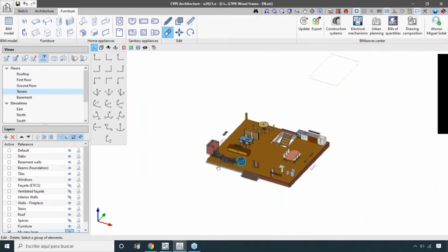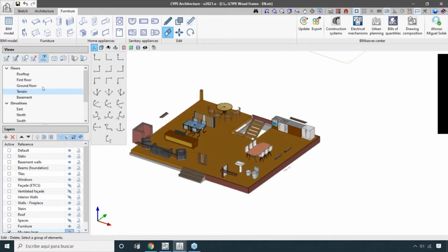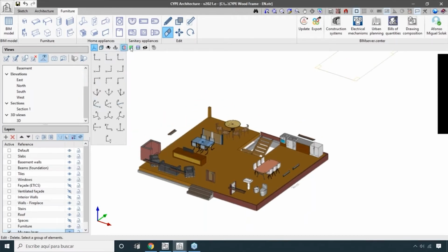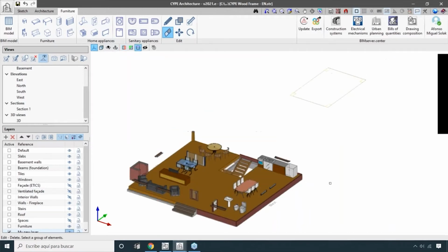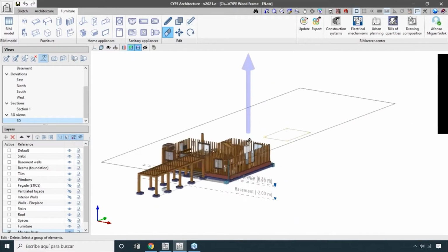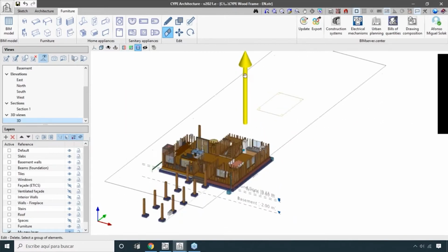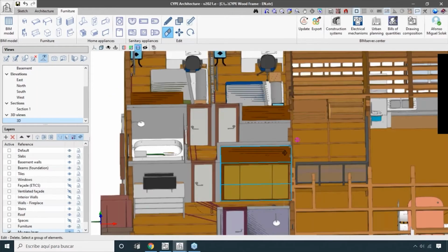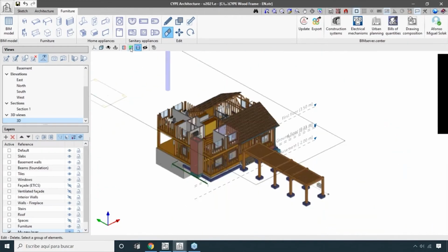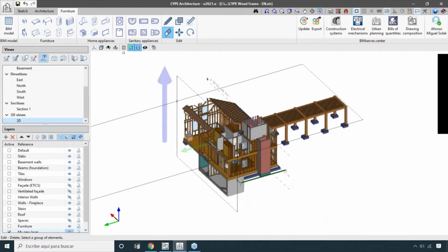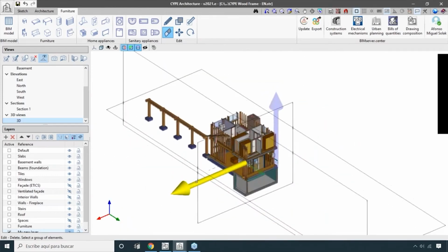All right, more things that we have here. In some moments, we can create these sections, these elevations, these floor plans, these 3D views, but sometimes we can also use these three sections that we have here. They are very useful. They are temporary. We cannot save the position of these sections, but sometimes we can use them just to have a fast overview of something that is inside of the building, for example. You can just use one of them. You can also combine two of them, for example the green axis, the blue axis, and also the red axis at the same time, no problem.